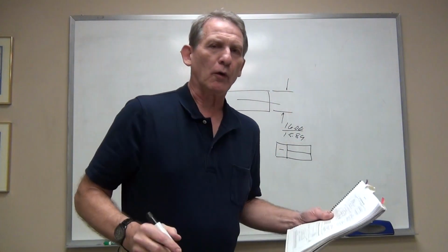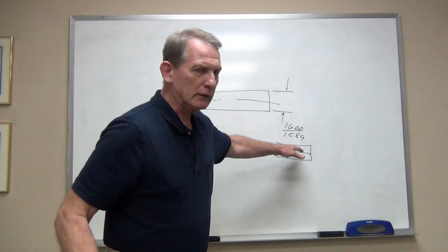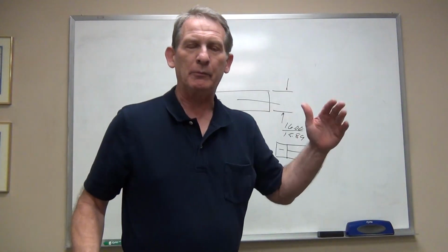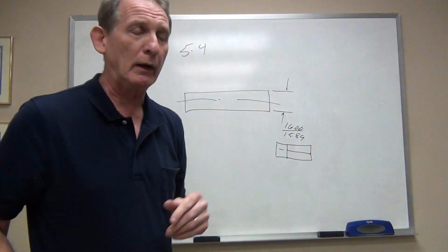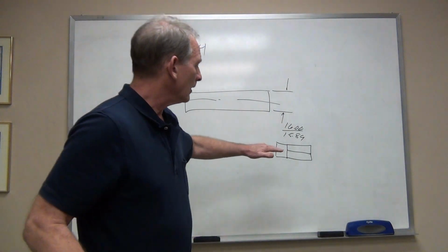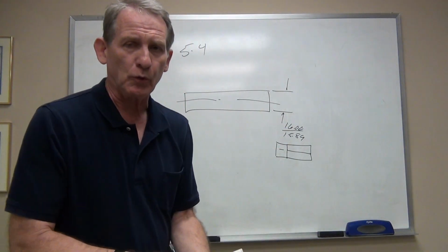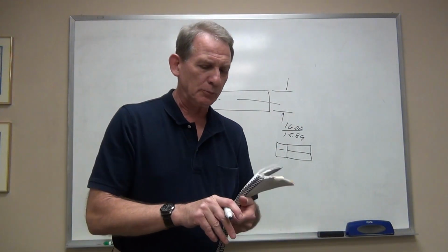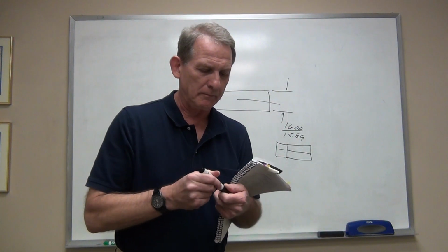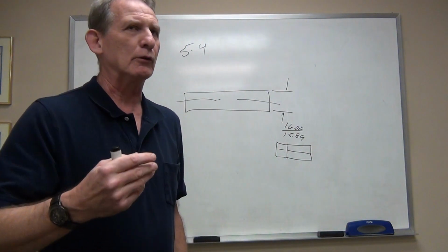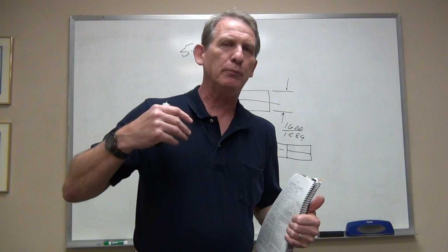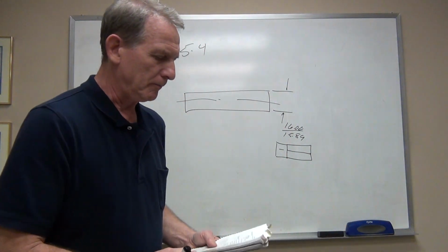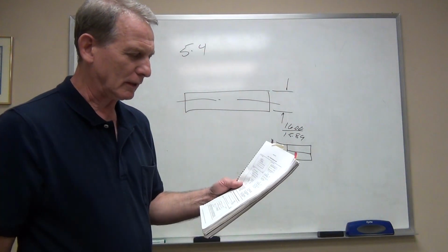Okay, this form where you have the tolerance information stacked up one on top of the other is used in several ways in GD&T. This is a composite control, and it's meant to prevent that tolerance being applied all in one place. So, well, I'll show you what it would look like if it were.